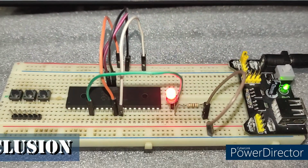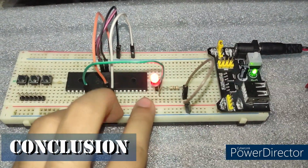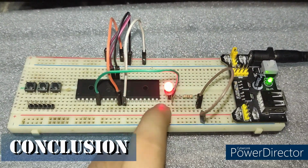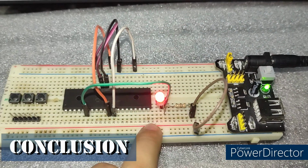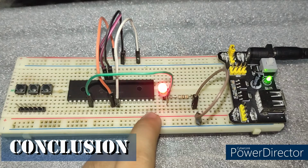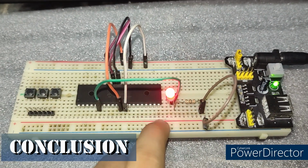So this means that if you want to make the adjustment of the brightness slower, you just have to consider a value lower than 10 as your increment for duty. But if you want to increase the adjustment of the brightness, okay, if you want to decrease the time, then you just have to increase the value of the increment for your duty cycle.